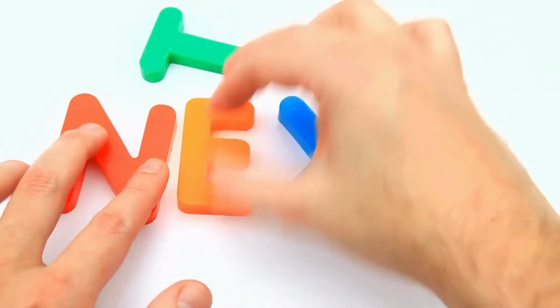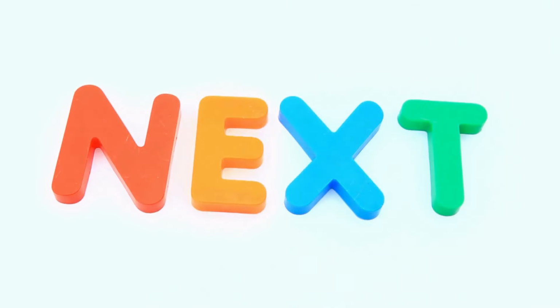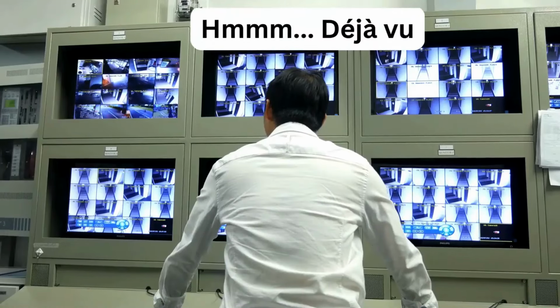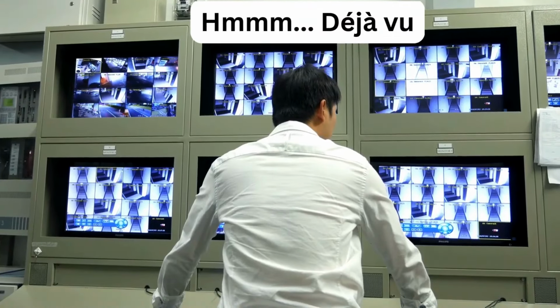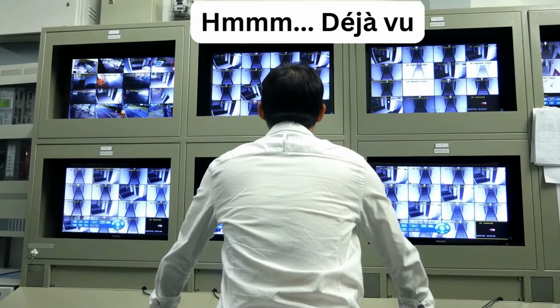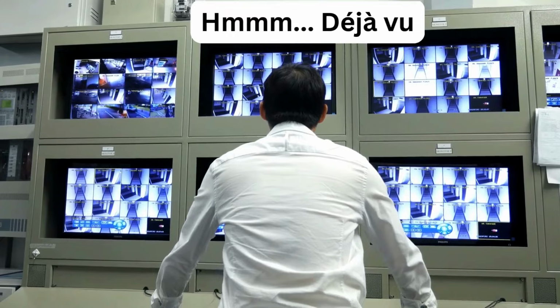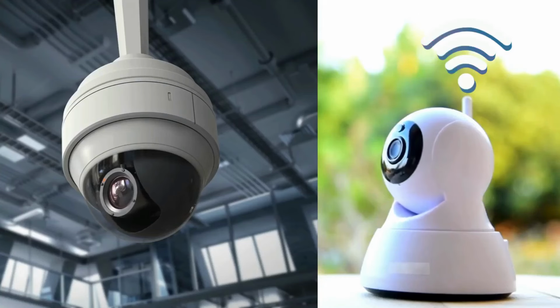Before we move on, let's quickly examine the vulnerabilities of traditional CCTV systems. First, the lack of encryption means that others could potentially view the camera's footage. Second, since the system is analog, it can be easily fooled by tampering with the output signal, such as feeding it an older recording without the security guard noticing. Third, because the system is analog, the video signal weakens as the camera's distance from the DVR increases. Okay, let's get back to the IP cameras.